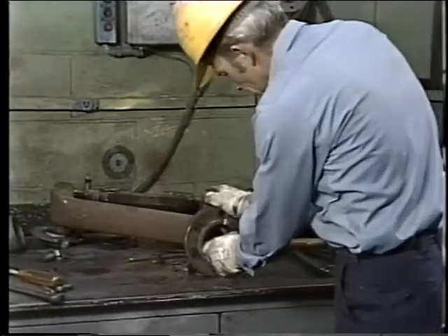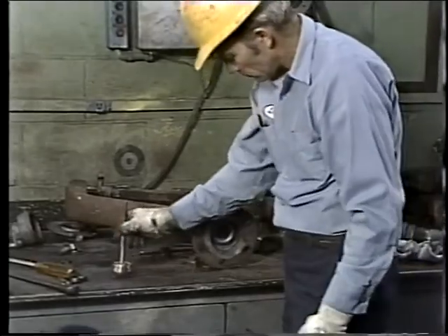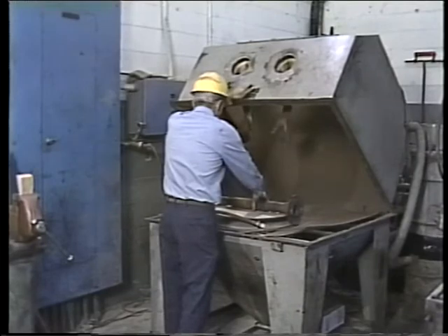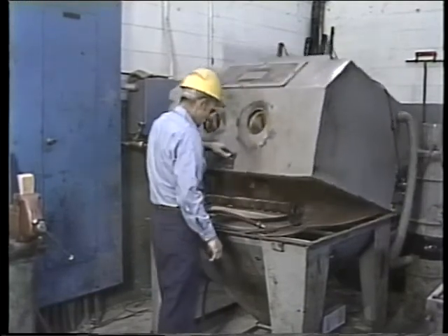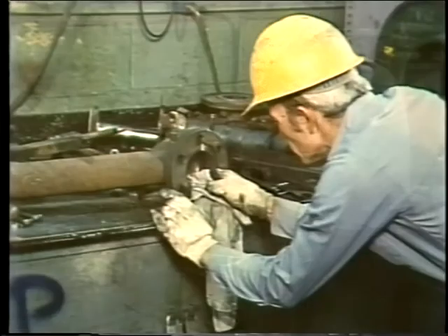Now we're down to the basic parts of this soot blower. In order to inspect the individual pieces, they need to be cleaned. The element is abrasive blasted, so it can be examined for cracking, erosion, and corrosion. On parts like the valve, the seat and disc can be cleaned with a shop towel using a little non-flammable solvent. When they're cleaned, the seating of the valve can be checked.